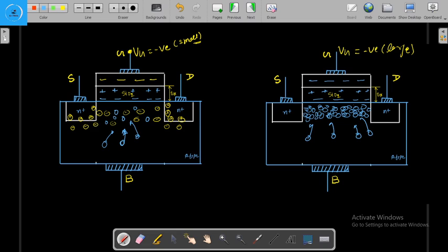And hence in this region the capacitance will be formed like this. This is the C O, gate oxide capacitance, and because the depletion region is not here, no depletion capacitance will be here, only the oxide capacitance, right?